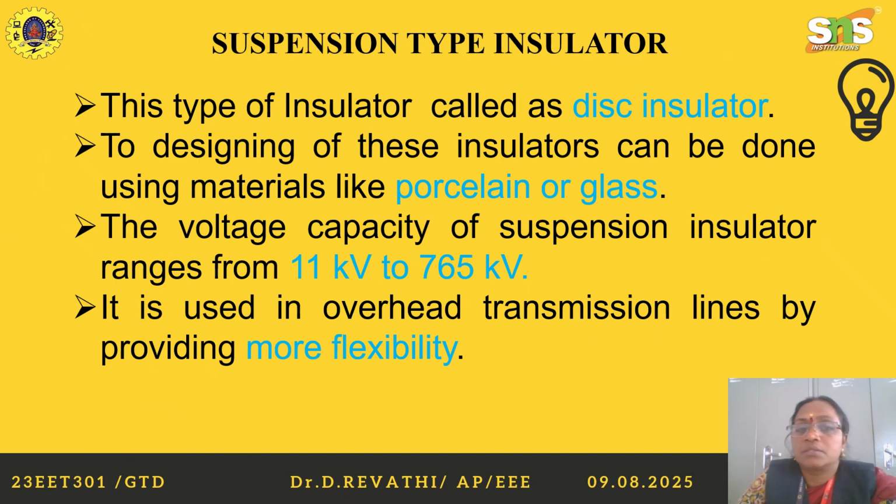Suspension type is also called disc type because of its round shape. It's like a disc. One by one we connect them in series. Two conductors are connected using a metallic link, and because it looks like a disc, it's called the disc type insulator, and it is made of porcelain or glass material.